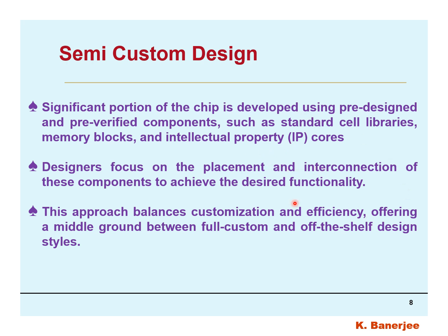A significant portion of the chip is developed using pre-designed and pre-verified components such as standard cell libraries, memory blocks, and intellectual property codes. Designers focus on placement and interconnection of these components to achieve the desired functionality. This approach is basically balancing the customization and efficiency, a middle ground between full custom and off-the-shelf design. So this is one trade-off or balancing option between full custom and off-the-shelf design. In this semi-custom design, the gates or components are pre-designed and in fixed location